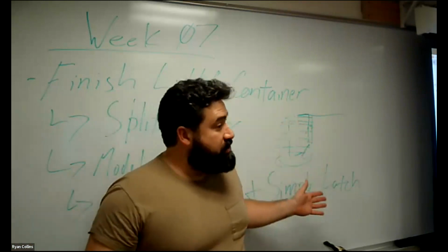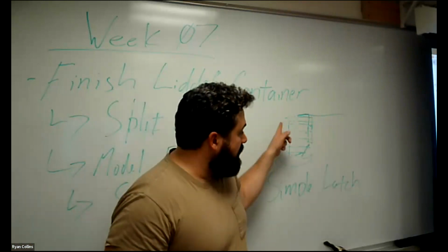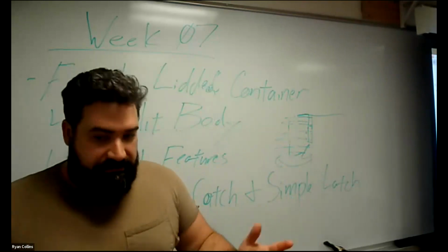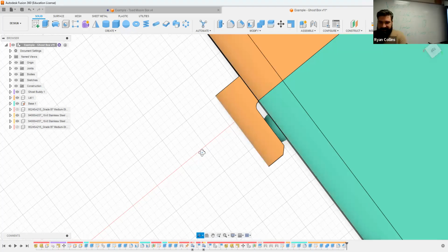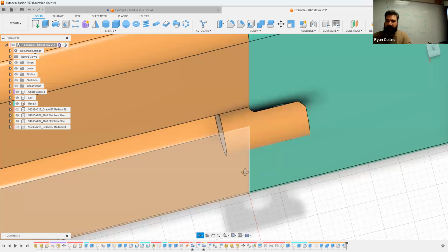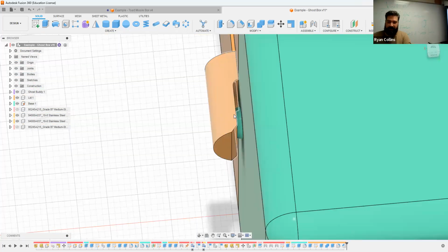So choose what material you're using, but remember, it's all sliced up like that. So just something to think about. Like I said, you can add fillets, add strength to this. That would definitely help. The amount of overlap that we have here is very minimal, so this would probably work really well.